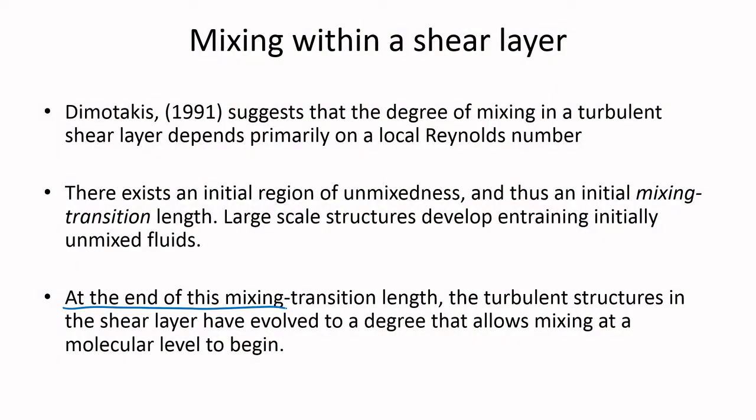So only this fluid mechanical development of large scale structures does not immediately allow for mixing. Only after some straining has been inflicted and some large gradients of species have formed can the mixing start.